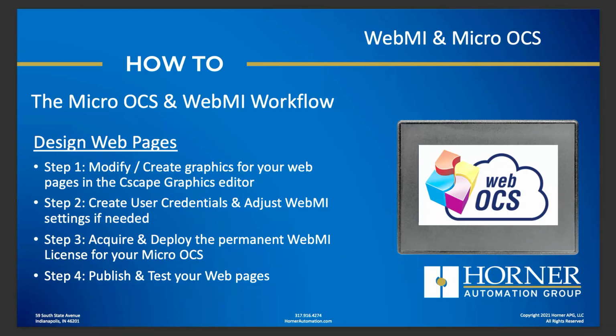Okay, so that's really the workflow, if you will, for applying WebMI on a micro OCS. Start with your original file, duplicate, rename it, change the configuration, go in and work on your web pages, add user credentials, make sure you're all licensed, and then publish and test. That's pretty much the workflow. All right, now let's go ahead and go to a live demonstration.